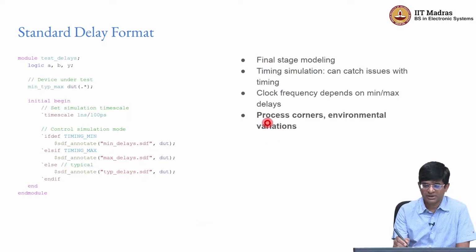And as I said, there are a number of different variations that can happen due to either process corners or environment variations or voltages and so on, which could potentially be caught by running simulations under different kinds of timing scenarios. And this SDF is a way by which different timing parameters can be specified to the simulator, and it can take those parameters and actually simulate them in all conditions, right.